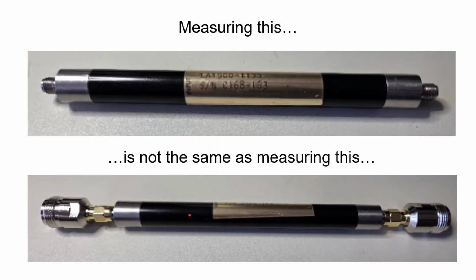Let me illustrate it with this. This is a picture of a low-pass filter with SMA connectors on it. Measuring this is not the same as measuring this. Here we've added the adapters, and these adapters affect our measurement. So if my reference plane, I know I'm taking liberties here with the connector types, is out here instead of right here, then I have added whatever loss, albeit small or large, is contributed by this adapter here and here. So these two measurements are not the same. All that just a plug. You got to protect your reference plane.